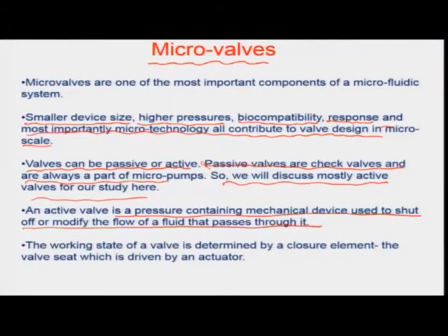And in this kind of circumstance, typically the working state of a valve is dependent on the position of the closure element, and the valve seat, which is actually the closure element, is driven through an actuator of some sort, which is based on a variety of physical principles. We are going to look into the design aspects of two different such principles. One is the pneumatic design, and another is a thermopneumatic design of an actuator which would contribute to microvalving of the flows at that particular length scale.